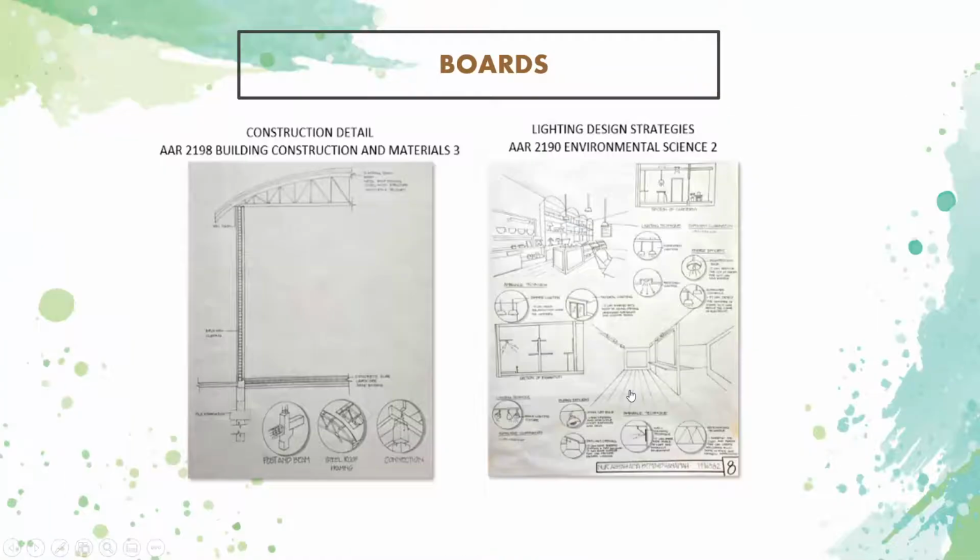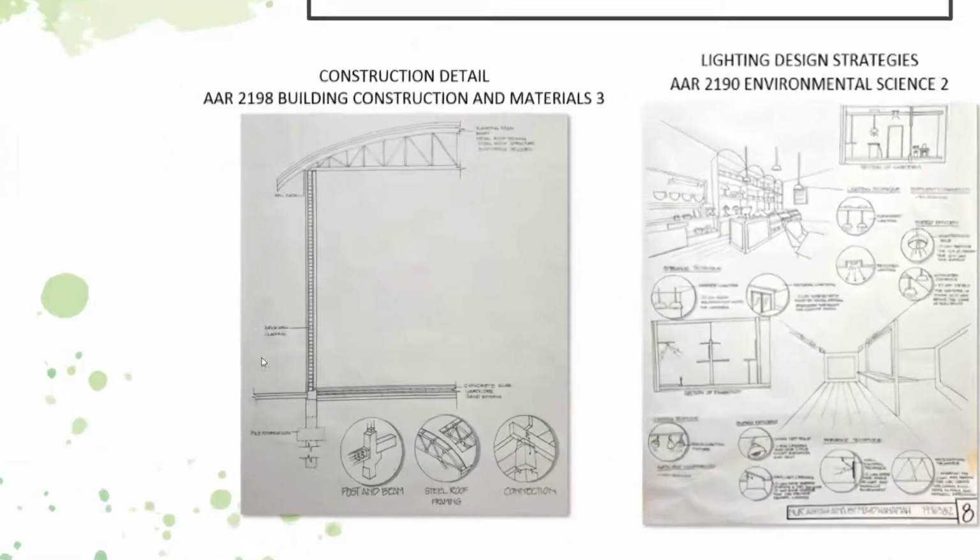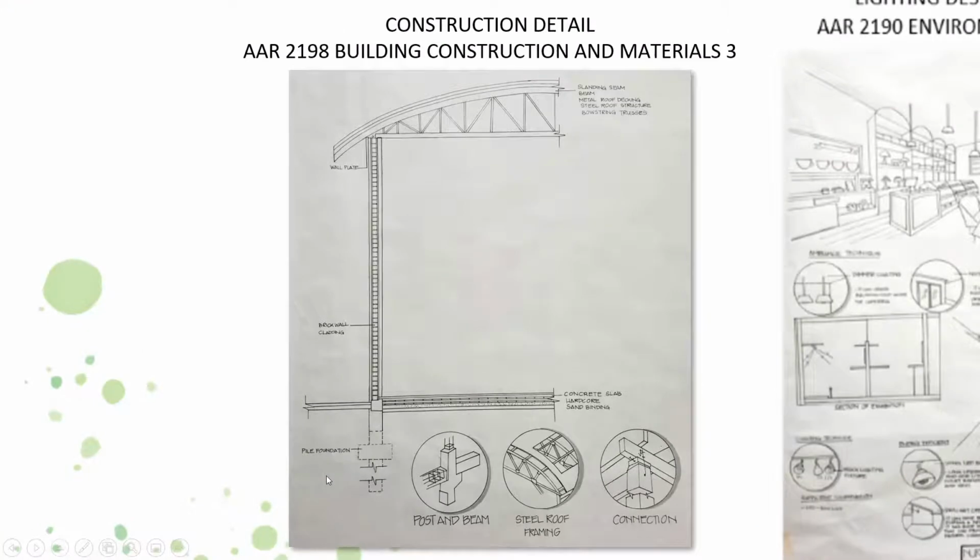Okay, next we move on to the construction details. As we can see from here, the suitable foundation that can be used is pile foundation because it can hold the friction of the soil, especially in coastal areas that have medium, fine, and coarse sand. Next is the floor construction, which is concrete floor slab since it has high durability. And for the wall, a masonry brick wall can be used because it can adjust the temperature of the building by storing heat and cool air.